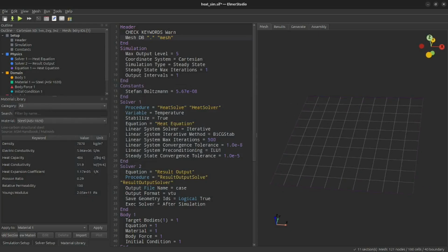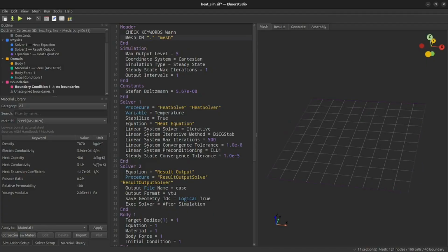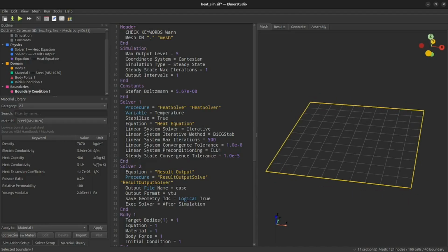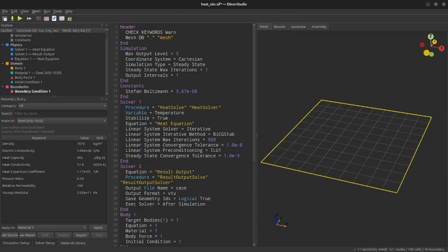Now I have the mesh. The most important part in my simulation is, remember, I have to set up the boundary condition. But as of now, if I click on a boundary of this plate, you can see that the whole thing is just one boundary. When I generated the mesh, there were options to create these boundaries, but I wanted to show you how you can do it when you bring the mesh to your simulation. So as of now, there is only one boundary.